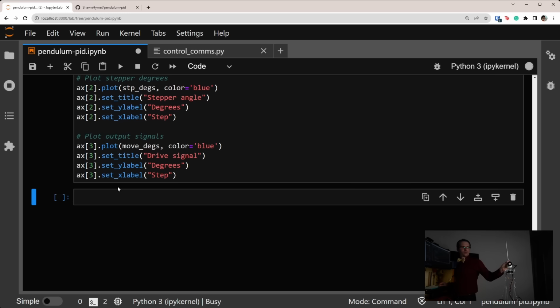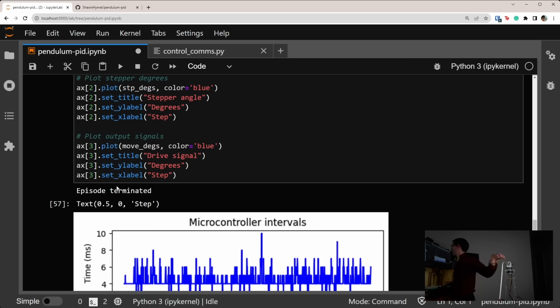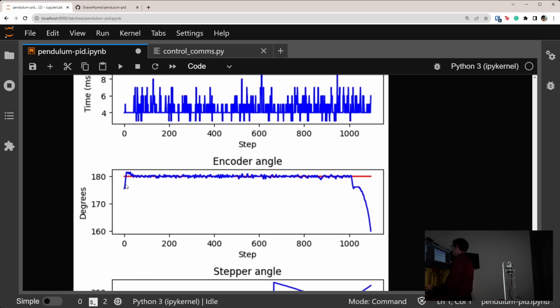And what happens if we take it really low, like 0.001? Once again, it's pretty good. We can't really go too low with this. I'm going to stop it there. All we're trying to do is suppress this peak here, or any of the peaks where it overshoots our set point. And in this particular system, an inverted pendulum, we don't mind a little bit of overshoot.